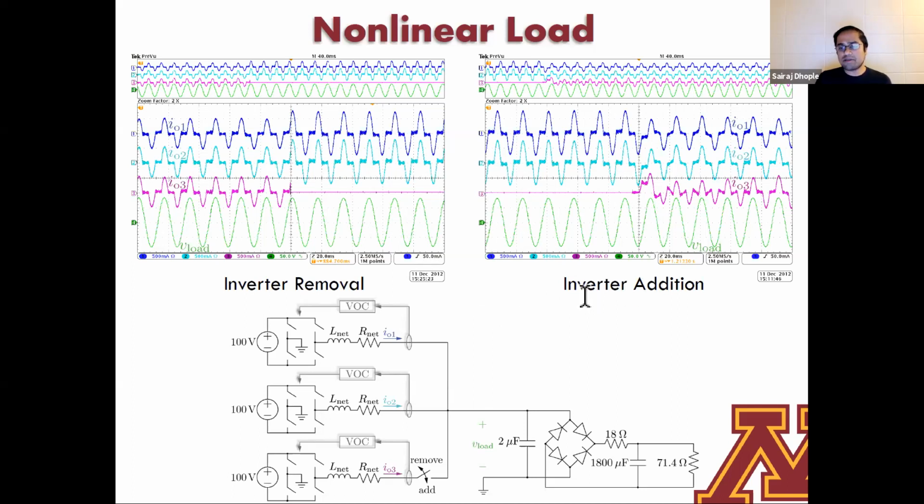What happens if I throw in a third inverter? Well, you have two of them that are providing the load power. At this particular instant, I bring on the third inverter, and you see the other two automatically kick back on their power production, and then I'm able to satisfy the load through this large signal transient. And really, the point I want to make here is that, hey, look, I had a very nonlinear load, and still things end up as desired and as engineered in order to get me my load voltage, in order to get me this dynamic performance, which is really quite fast.